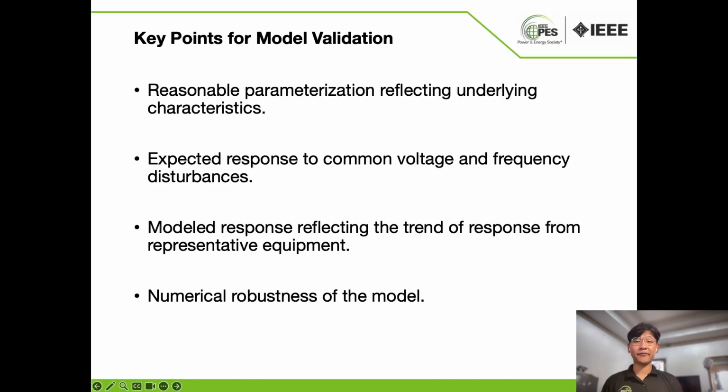The model validation process provides direct comparison between the simulation domains and the actual product performance. Generally, real product performance should be validated against an identically parameterized EMT model of the IBR unit. In this comparison, both the IBR models and the product response are expected to match with a tight tolerance after accounting for measurement accuracies and simulation software nuance. This process is also known as type testing.